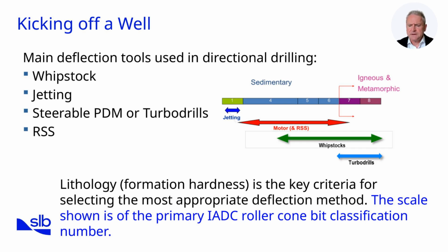When the formation becomes very hard, in the region of 30,000 psi and greater, normal bits are not strong enough to drill, and we need to move to impregnated diamond bits. These bits drill by grinding on the formation, which is a very slow process, so we run them with turbo drill motors. These are high RPM, low torque motors, often spinning the bit well in excess of 1000 RPM.